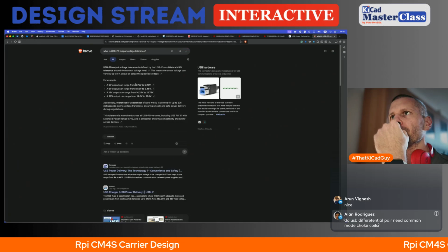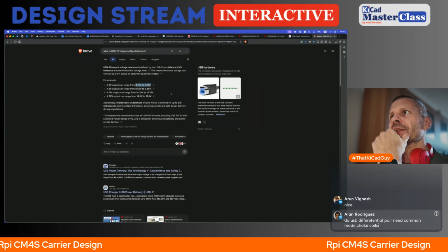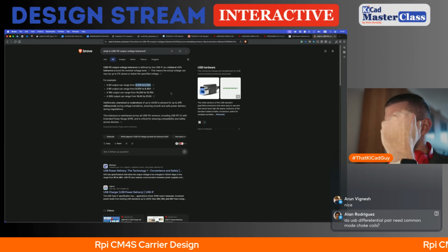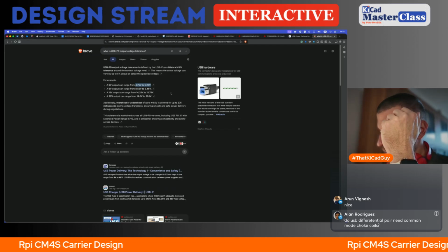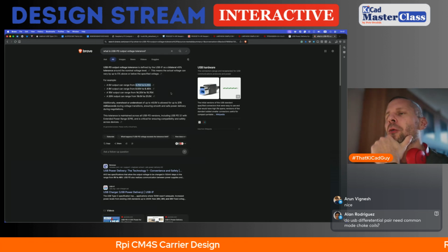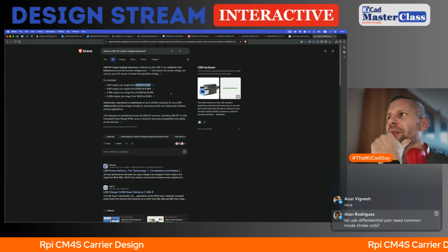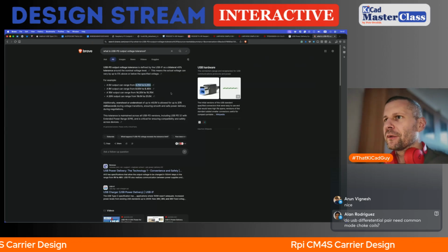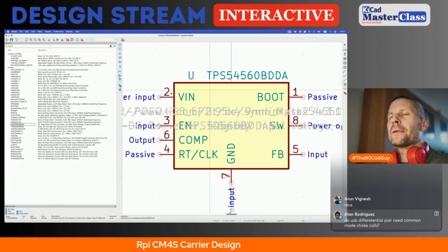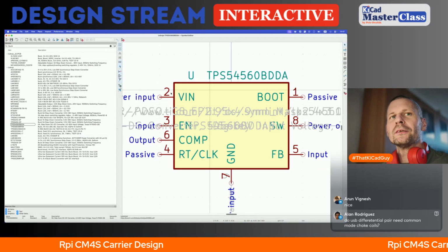Yeah, 5% they say. Okay, so when we get 4.75 and the thing has 97%, it's 4.6, which is almost at the lower tolerance of the 5-volt CMOS logic. So not good.